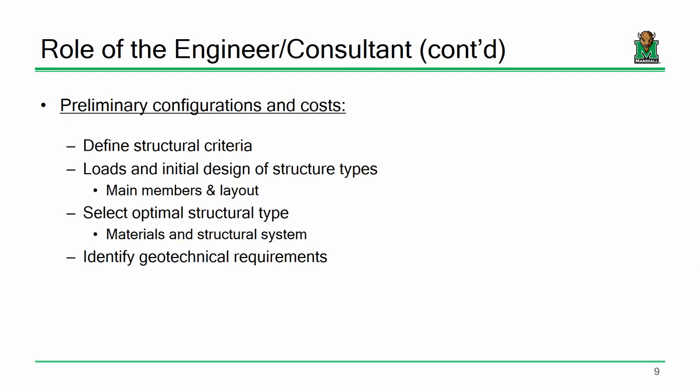Make sure you've got the criteria down pat, maybe come up with some rough ideas of how deep the beams need to be, the size of the columns, what type of structural type you're going to use. For instance, you think about this. This is a steel framed system, but right down the road, 3rd Avenue parking garage, that's a precast concrete structure, right? Different structures are more appropriate for different systems. Just depends on what's going on.